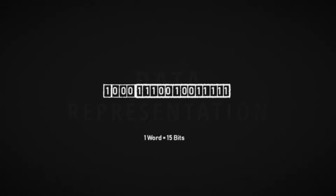Now that we know about the memory hardware, we will have a look at how data is represented within the computer. The basic memory unit is a word. It contains 15 bits plus 1 parity bit. Every time a word is loaded from memory, a circuit checks whether there is an even number of ones in a word. The parity bit is always set in a way that it makes the number of ones even. When the 15-bit word contains, for example, 9 ones and 6 zeros, the parity bit will be set to 1, so that the total number of ones becomes 10 and is thus even.